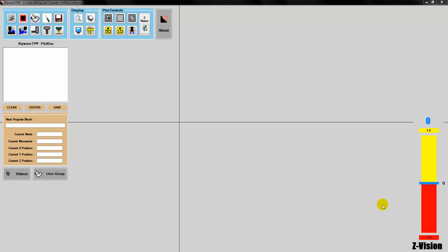This demonstration came from a request from a customer of ours who has a post processor that outputs a standard FANUC style program. But he has some older machines in the shop. One of them requires that the program coordinates have no decimal points and leading zeros. And the other machine requires no decimal points, no leading zeros, just standard no decimal point format. On the machine with the leading zeros, the X-axis is also a radius designation rather than a diameter designation. And his post processor outputs a diameter for the X value.